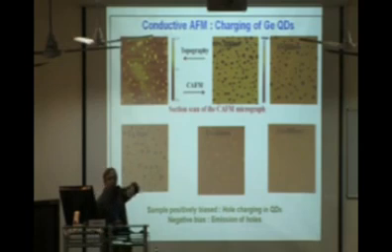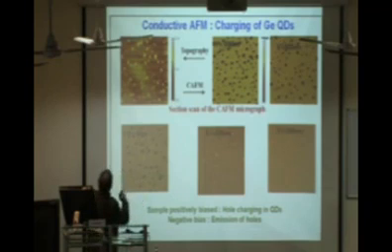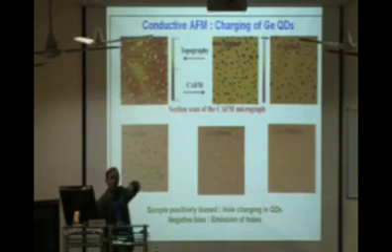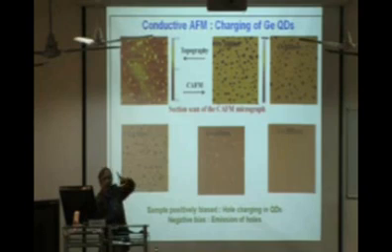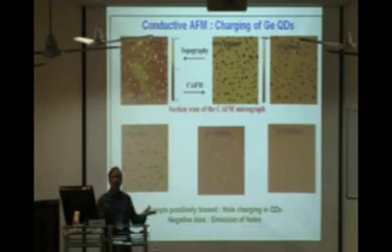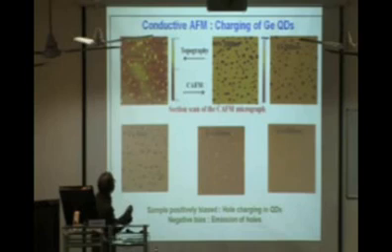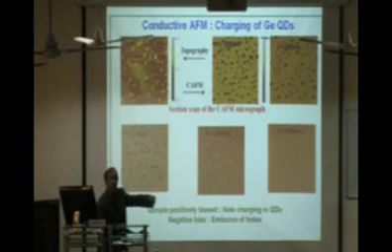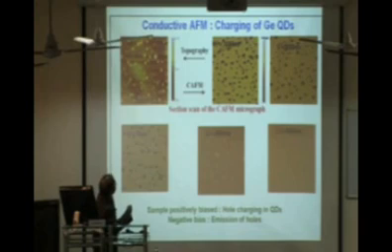I know atomic force microscopy is used to do the topographic image of quantum dots. So this is the sample that we have taken, the topographic image of the quantum dots. Now if you use a conducting tip, and we come very near to these quantum dots, and take a current contrast image, we exactly get this kind of structure which replicates that topographical image. So this is the current contrast imaging that shows that charges are actually transferred to the quantum dots when you apply bias. In this case, these images are taken at V equal to 300 millivolt, 500 millivolt.